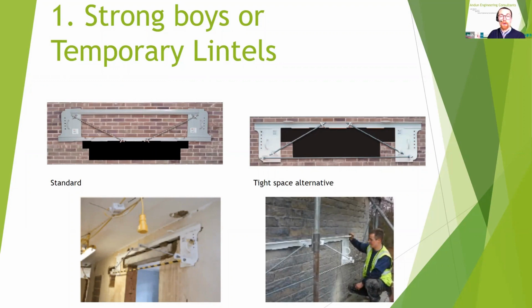However, it does rely on that masonry arching effect that we discussed earlier. Therefore, it can't really be used near corners or near any openings.